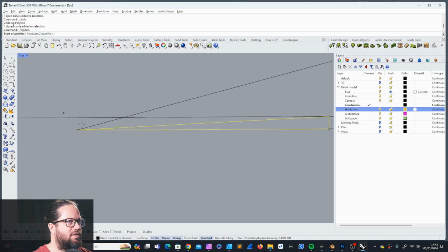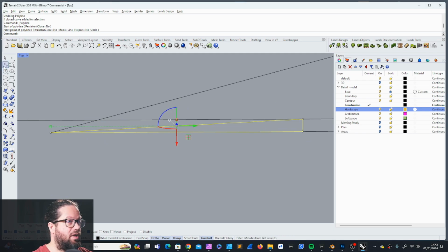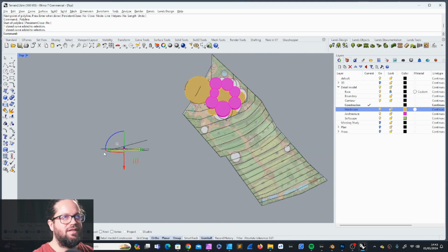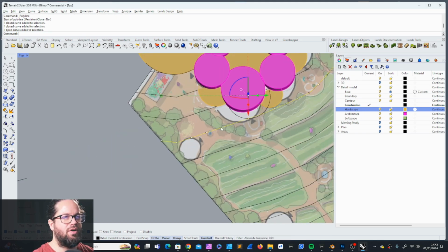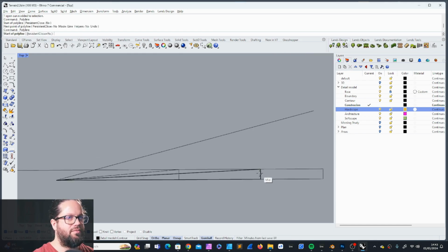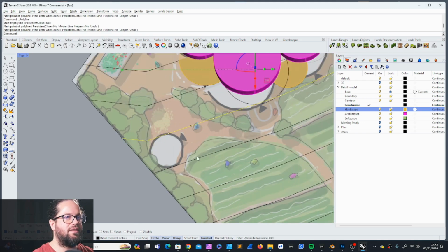Now, what is still comfortably walkable, let's say, is a slope of 1 to 12. So we could try to fit 20 meters into a distance between these lines, because we know that 1 meter, this by the way is half a meter. So half a meter would mean, if we take half of this, a distance of 10 meters. We would require a distance of 10 meters.